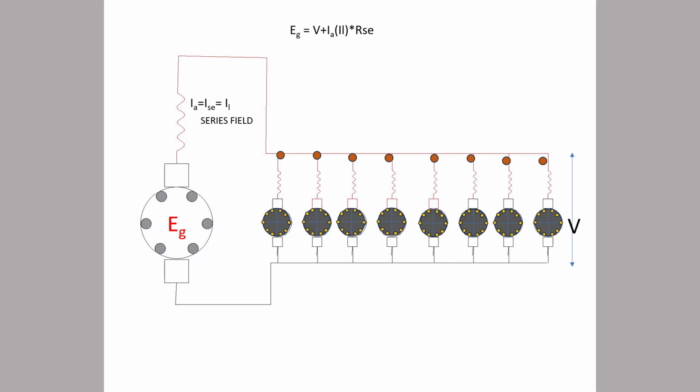25 kV supply, stepped down by a transformer. Then the required voltage for the motor is taken in AC form, and then it is rectified with a bridge circuit into DC, but it is a pulsating DC. We need smooth DC, so we are using filter circuits like smoothing reactor and capacitor.